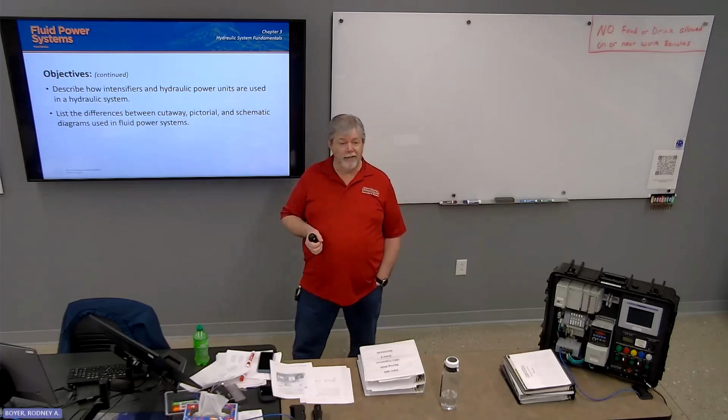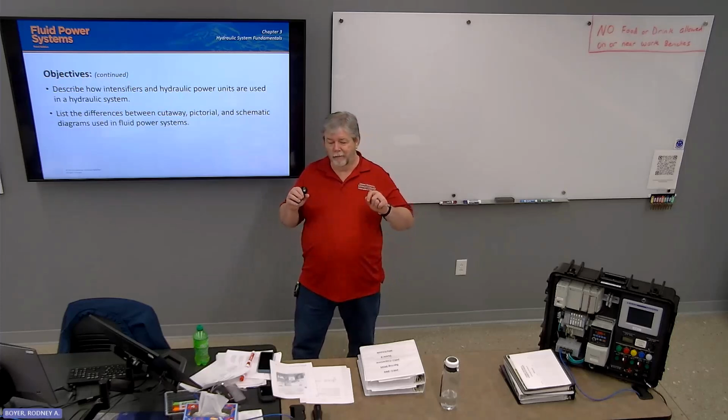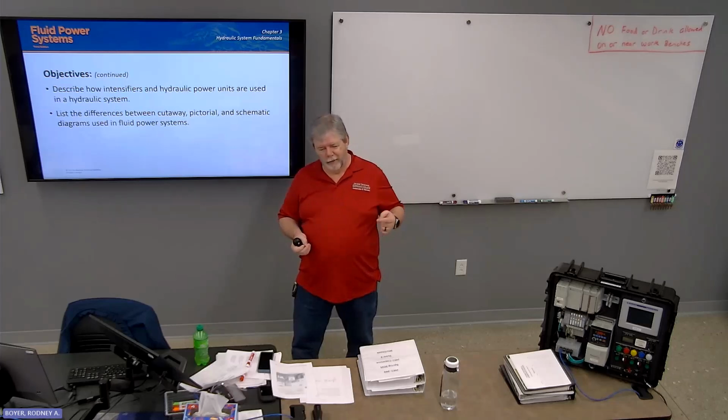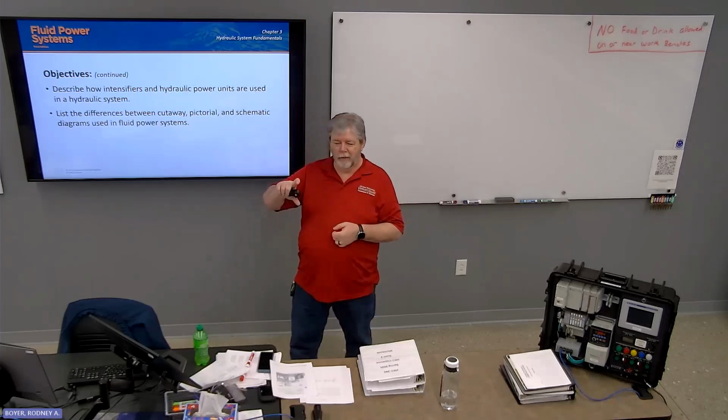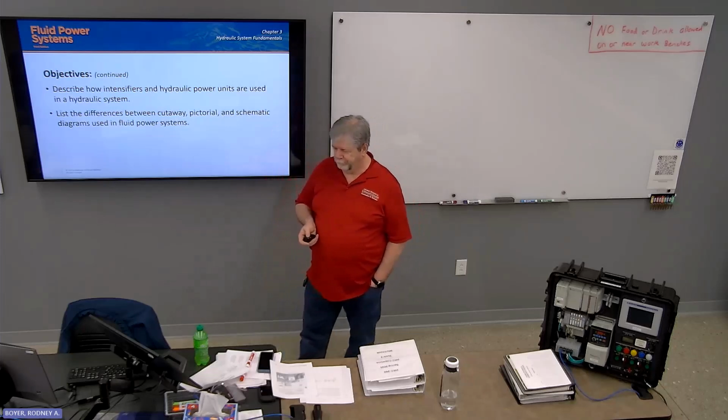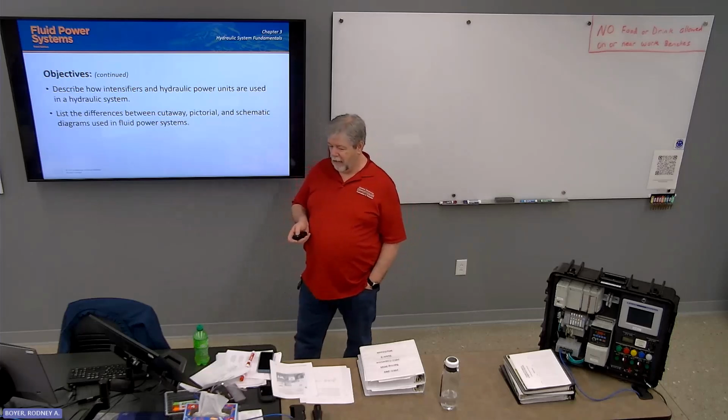All an intensifier is, looks kind of like a step down cylinder, I guess, for lack of a better word. A large diameter piston on one side and a small diameter piston on the other. Whatever pressure you put into the large diameter is multiplied to the smaller one, which is kind of cool. List differences between cutaway, pictorial, and schematic diagrams.